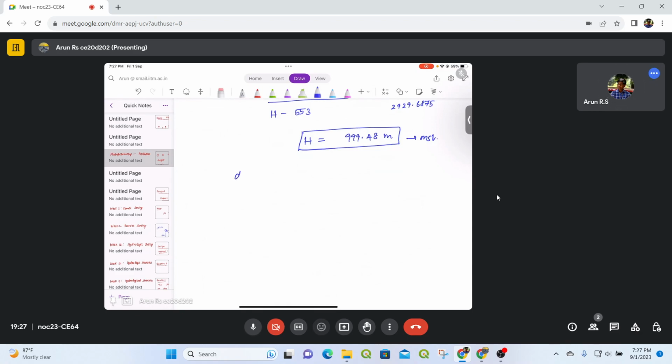So our relief displacement formula, d is equal to h into r divided by, it should actually be capital H, but since we need it with respect to the base of the tower, I'm going to subtract the h average of the terrain.